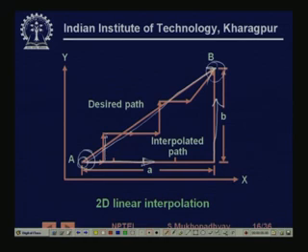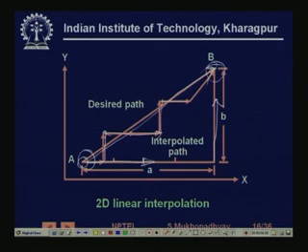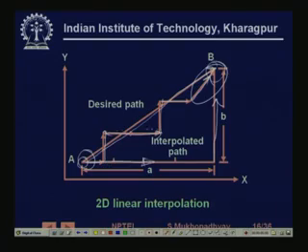In the second interval a y pulse is given and no x pulse is given. Then two consecutive x pulses are given, a y pulse, an x pulse, and here both x and y pulses are given. So since both x and y pulses are given, the table actually moves along this direction because both the motors are now rotating simultaneously. So this has to be determined.